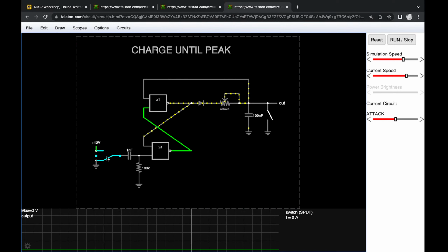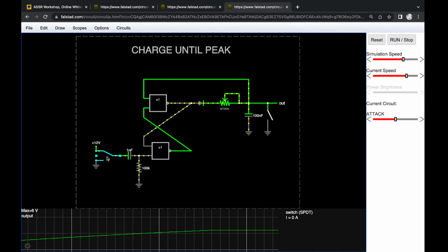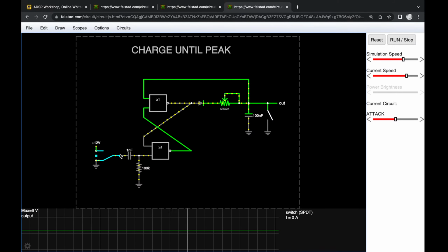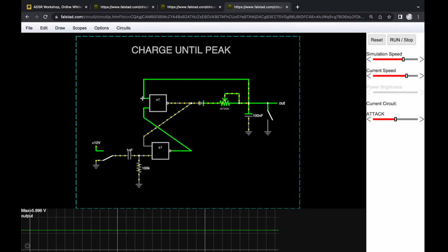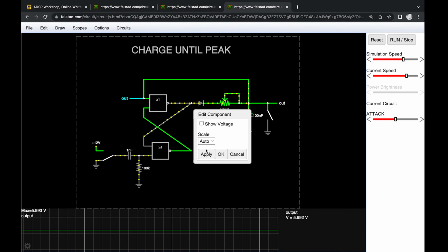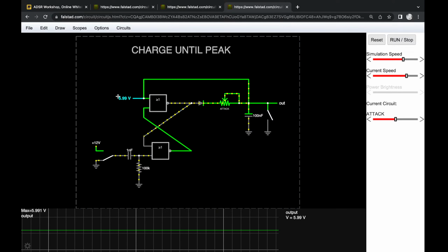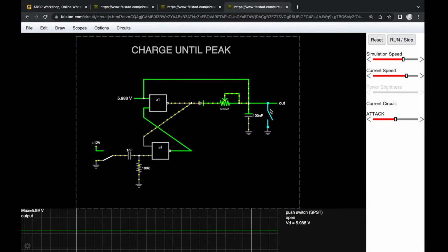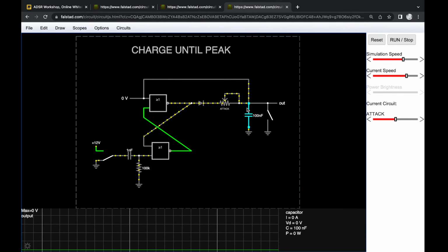Okay, so I'm going to trigger this thing. Boom. You saw that? What happened is I turned the flip-flop on, it charged the capacitor, and then when this, wait, let me put a little output over here, and I'll show you the voltage at this point. Right, so we can see, that's because the capacitor is leaking, but it used to be 6 volts. Let me reset this, boom. That's what this switch is for, by the way. It's not really part of the circuit. I just have it here for convenience to discharge the capacitor instantly.